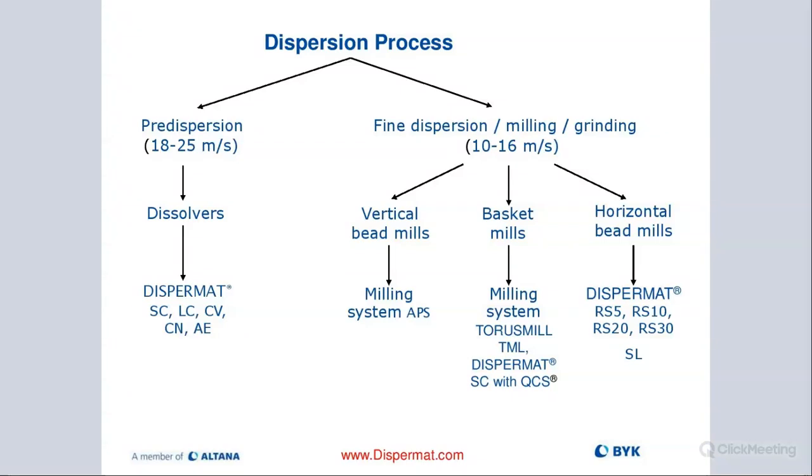What means most is the tip speed should be the same. The blade geometry should be the same. Again, cooling should be the same. So we have fill rate the same. You maximize all those things. Then you should have a very good way of upscaling from the lab to the manufacturing plant. But tip speed and blade diameter to vessel ratios are very, very important.